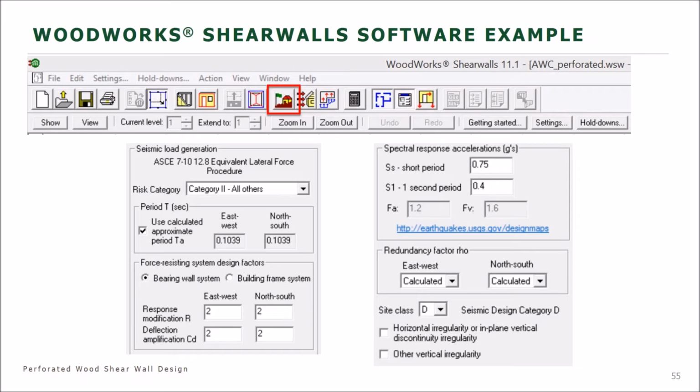On the right side, we can see all of the spectral response acceleration values based on the specific geographic location, as well as the site class we can input here. All these inputs are going to be combined in order to develop the base shear and the lateral load generation for the structure.